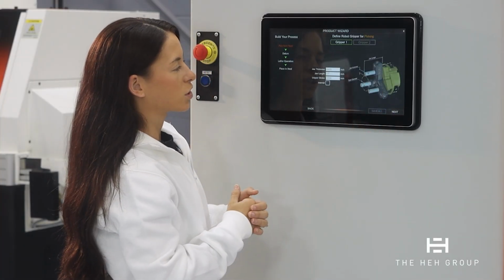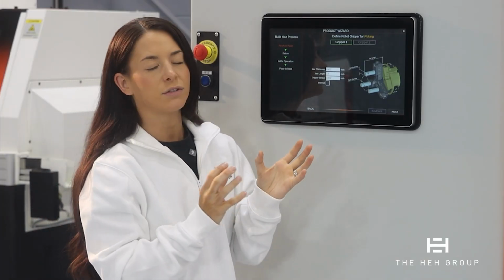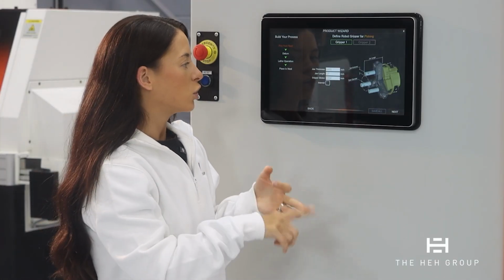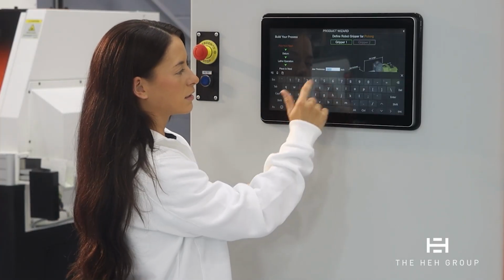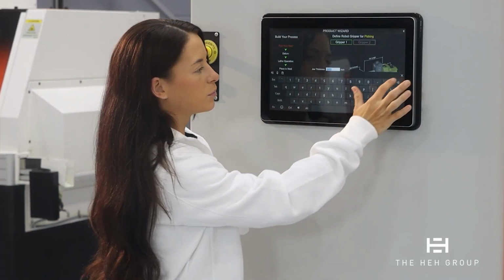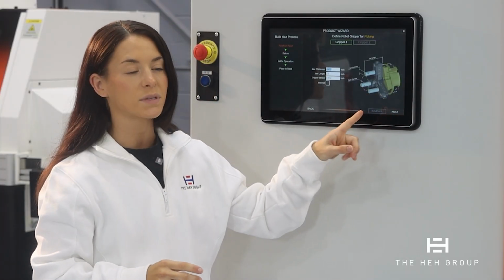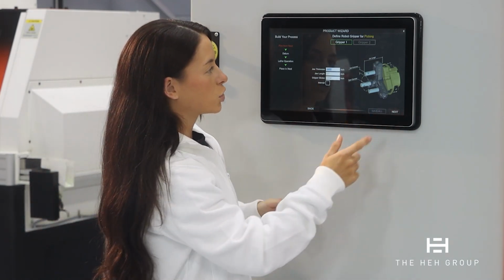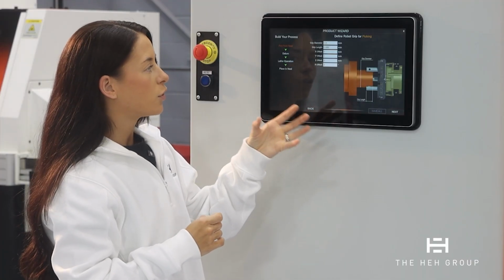Then you're going to go into next and define the gripper. This is really, really important. You want to make sure you have accurate measurements of the gripper. It's going to ask you for the jaw thickness, jaw length, and gripper stroke, and these are super easy to edit. All you have to do is touch this and type in a new number if you need to. The nice thing too is Agile has these diagrams that tell you exactly what you're looking for and exactly where to measure. So if we keep moving forward here, now we're going to define the picking for the robot.